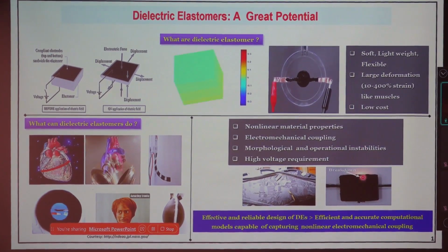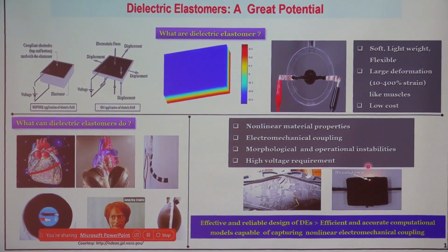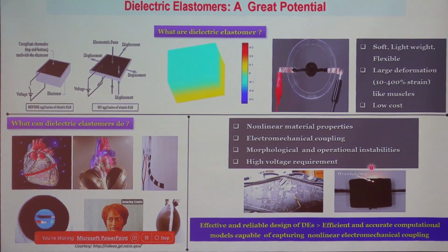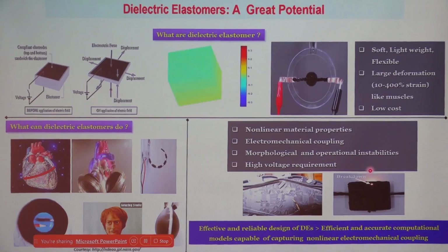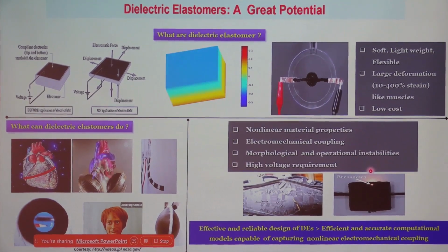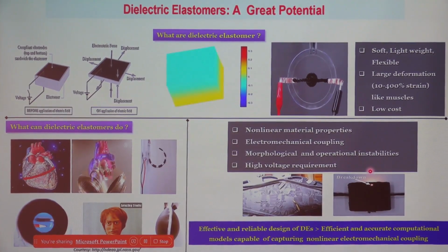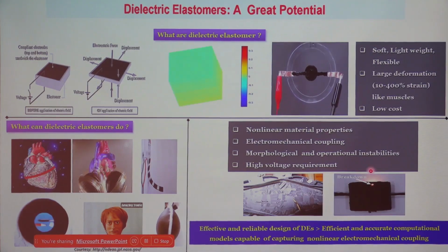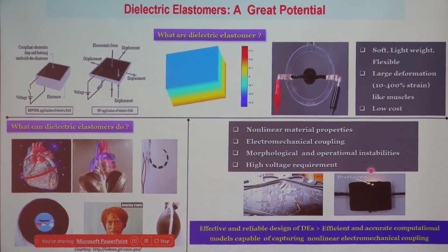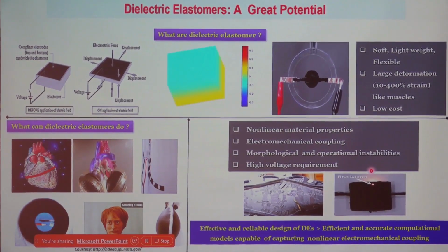You can see in this figure, as you keep on increasing the voltage, the membrane electrical breakdown will take place at a particular threshold voltage. That voltage is called the critical voltage or critical electric field that you supply, at which abrupt thinning of the membrane will take place, which ultimately leads to the failure of the device. Make my word clear: failure.